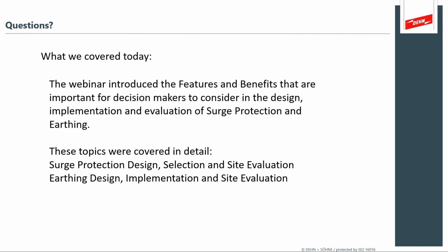Okay, great. Next question, why is it necessary to bond the door when the door is hanging from a metal hinge? Well, the metal hinge is essentially a casual contact. And as you'll see, especially when you have things like lights and instrumentation on that door, if the light socket breaks, you're now injecting fault current into the door, and you don't want to rely on the hinge as your electrical path.